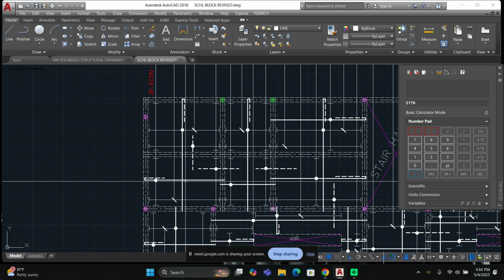So we have it said, please note. Number one, it said ground floor slab should be detailed as suspended. So what does that mean? It means the foundation is pile foundation. Yes.